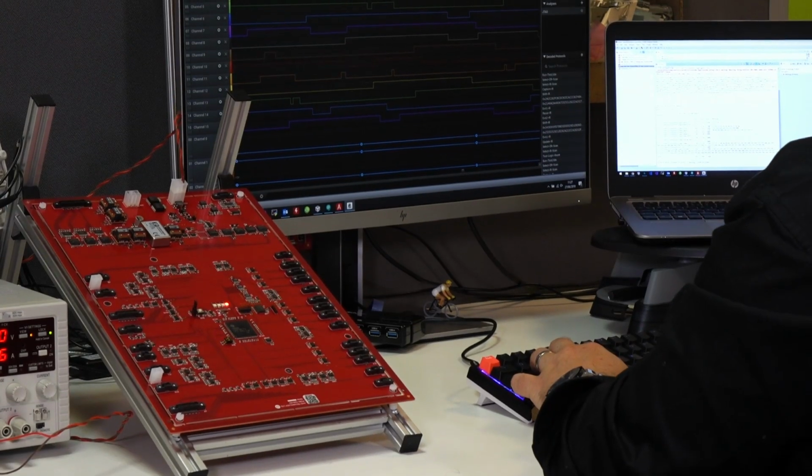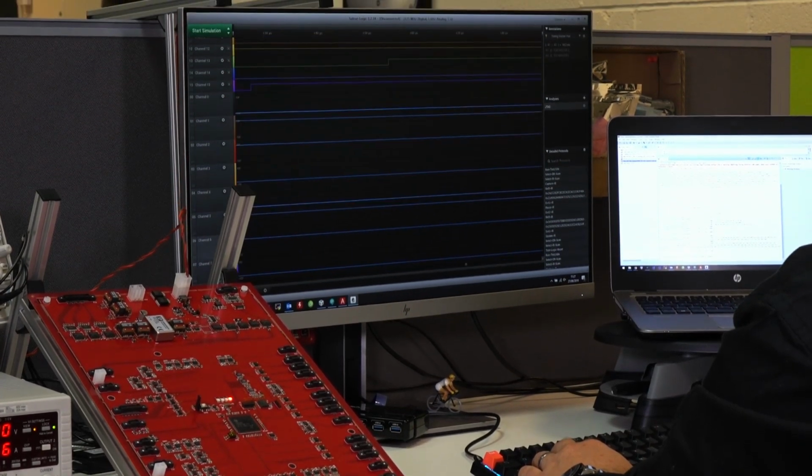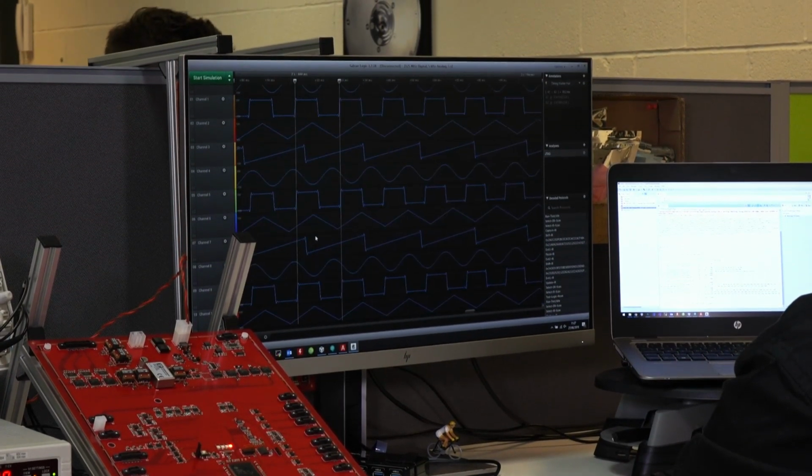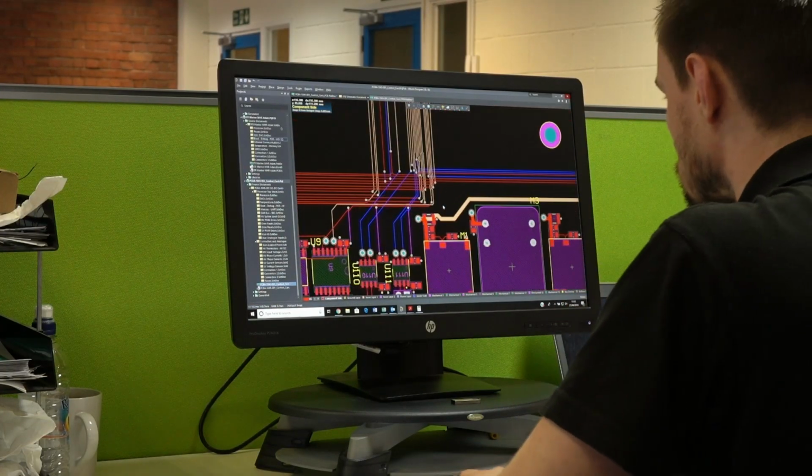For power electronics, we have to think about the electronic components that we choose and design, and the shape and the size of those, and how they're going to be integrated together. There's obviously the thermal aspects that we talked about. How we're going to cool that transistor, how we're going to get the heat out of that small area and into the water or the air, depending on the cooling method we're using.